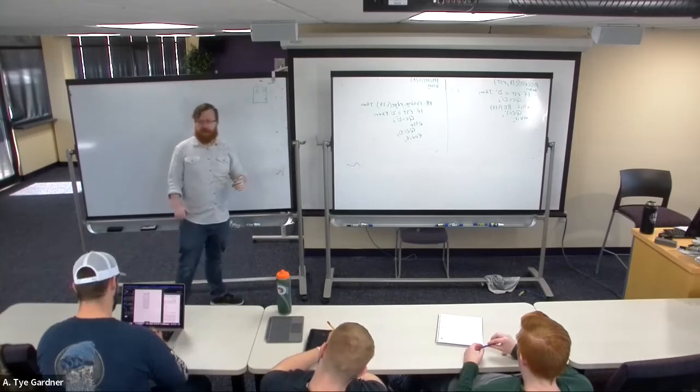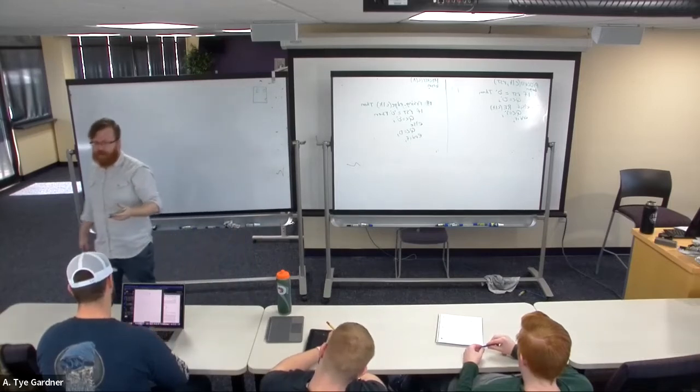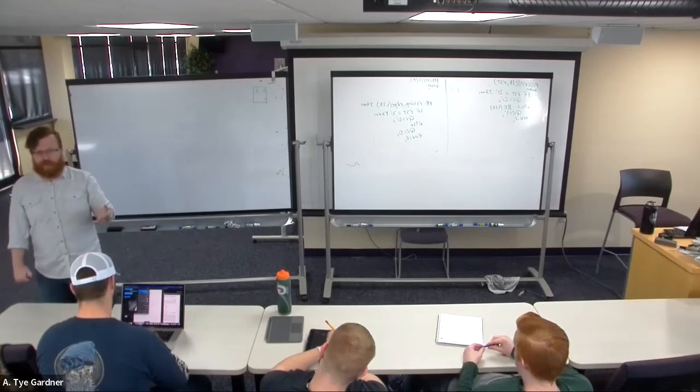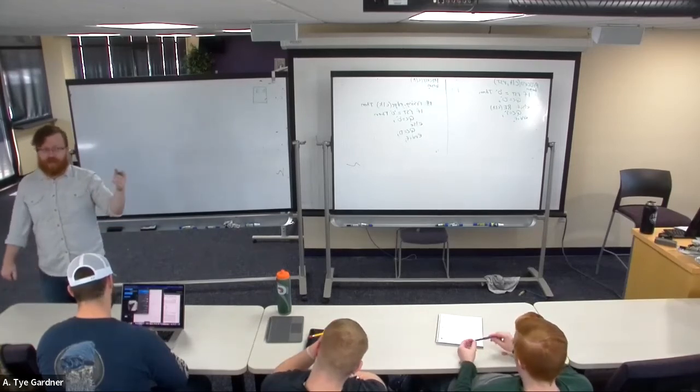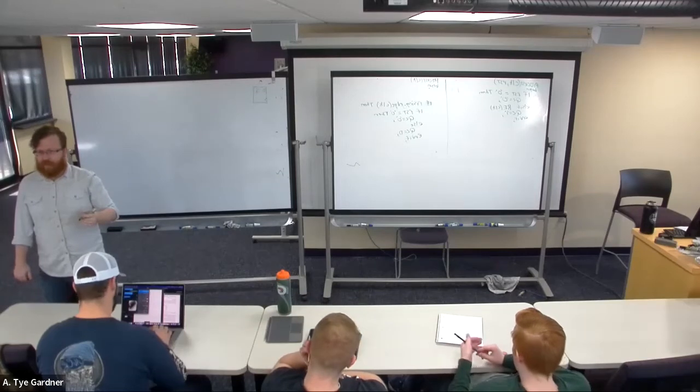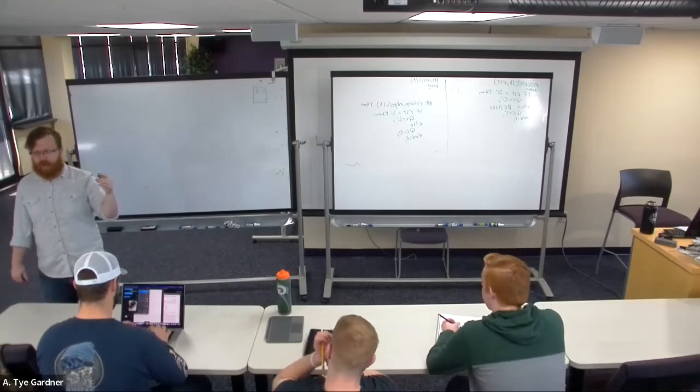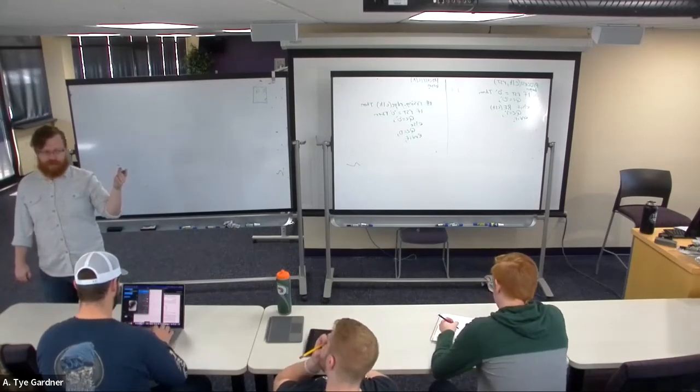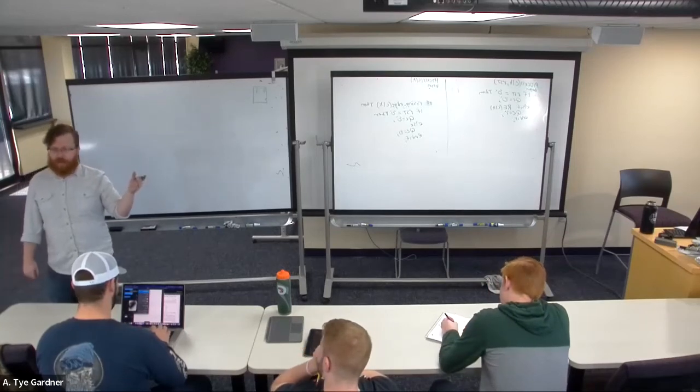And a clock enable says, I don't always want to care about what the data is doing. Sometimes I want to hold on, even if there's a rising edge of clock. I don't want to reset it. I don't want to make the data go away, but I want to remember this for a couple rising edges before I move on. How do we do that?